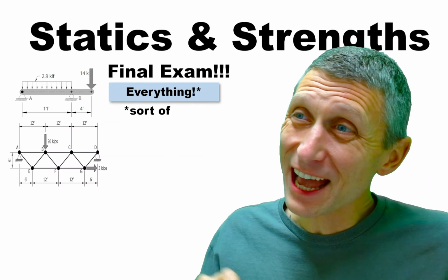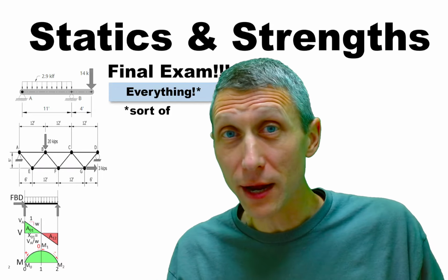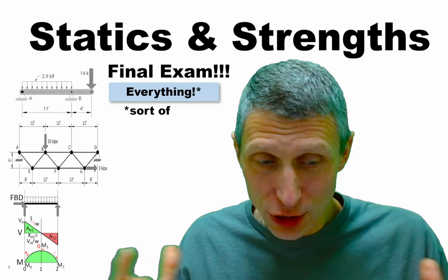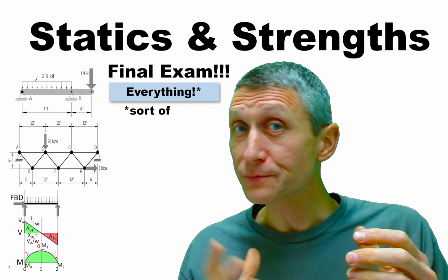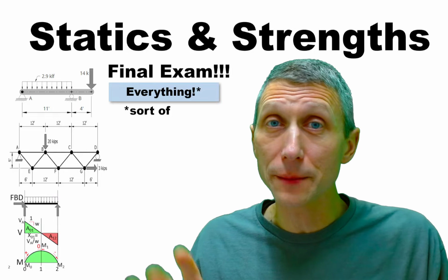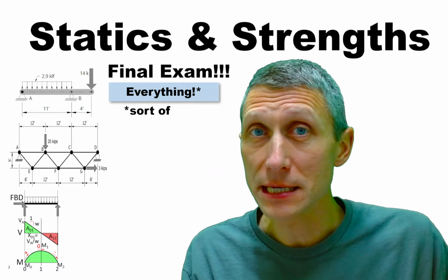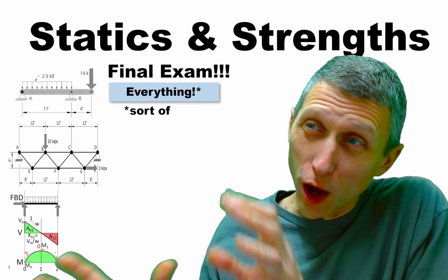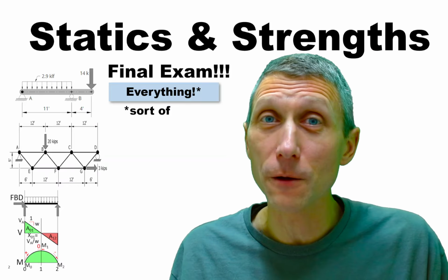So in addition to that, one of the things that really comes up as well are shear moment diagrams. Shear moment diagrams are so important. It's sort of like if you have a rope and you pull on that rope, you kind of know what the weight rating for that rope is. Well, when you look at a beam, you have to understand how much bending moment is in that beam to see if it's rated strong enough. So all of these things go together: beam reactions, trusses, shear moment diagrams to figure out the forces.